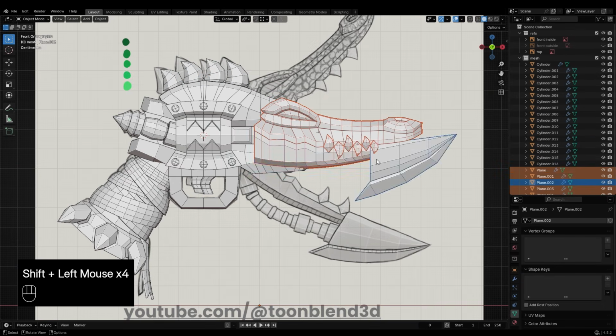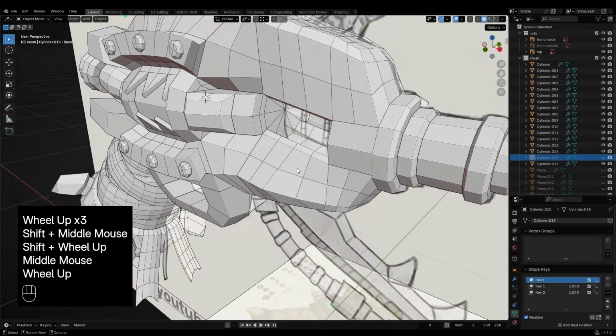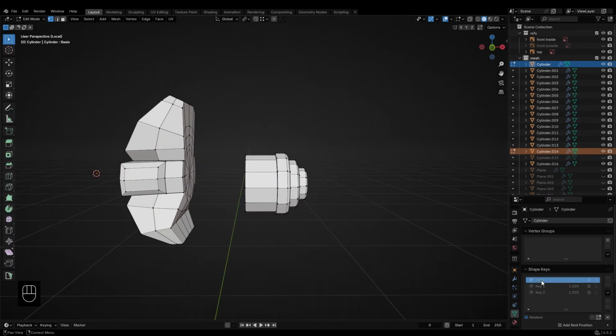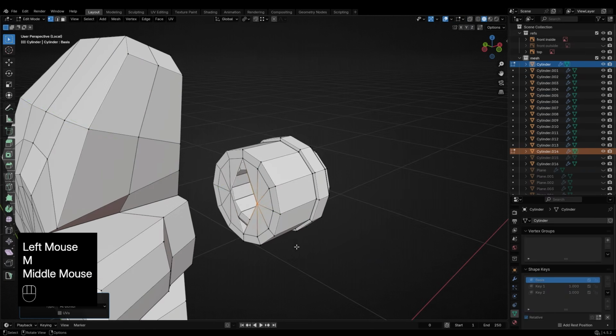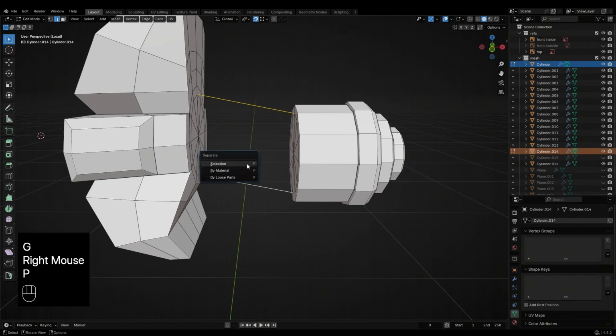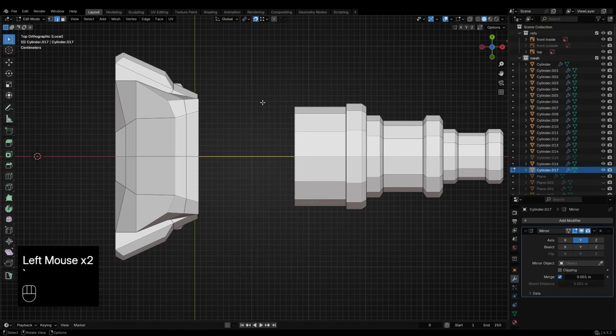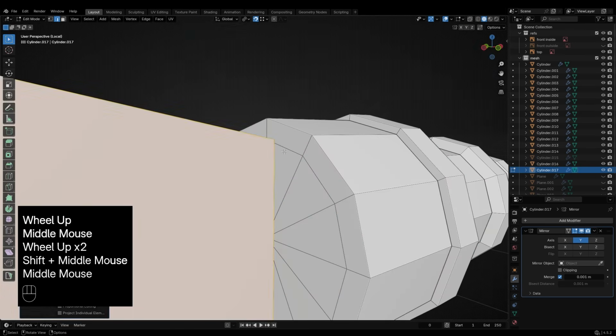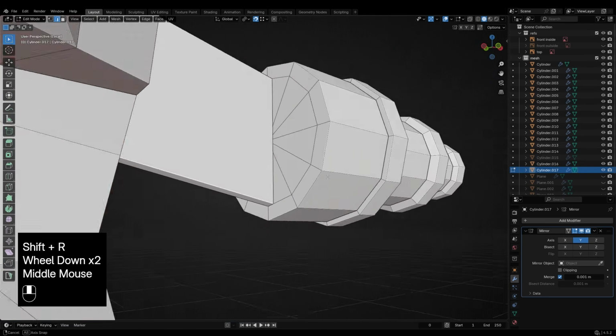Next, let's create the inner wall section. Before that, close the back part of the cylinder casing. Then create edges by connecting two vertex points, separate them, and fill the face. Extrude it sideways and adjust the vertex positions so they match well with the surrounding mesh.